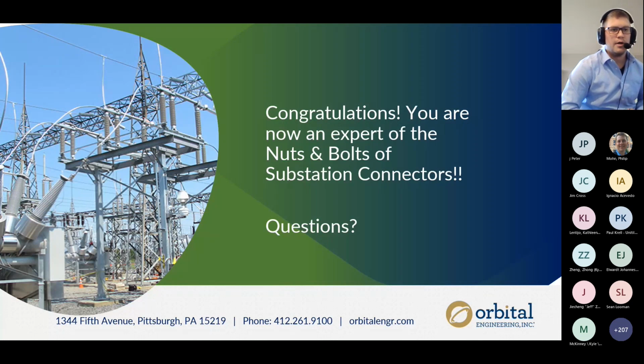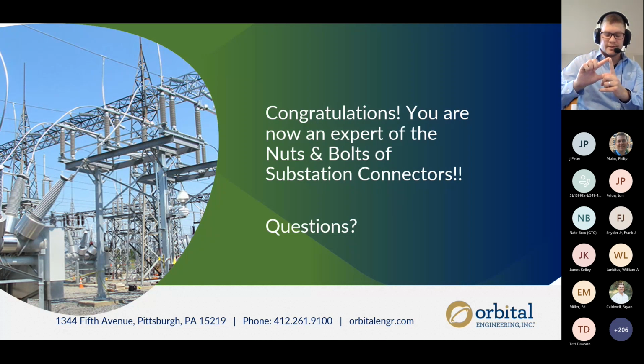So for rebar, I will say it's not particularly my area of expertise, but typically when you're going to ground a structure, you would connect from the ground grid, come up above grade, and usually right at the bottom of the structure, whether you have a little flange off the edge of the steel or a dedicated pad, is how you would connect to that. And I know some utilities I worked for would pigtail off of that and wrap around one of the rebars that come above the foundation grade. I hope that answers your question.